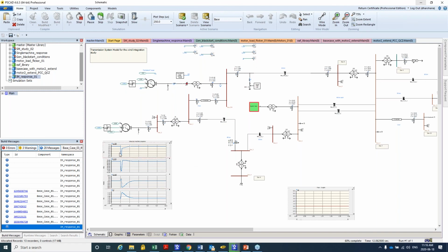And this delayed voltage recovery, the poor reactive power response, is because the rotor winding is just shorted. In a synchronous machine, the field winding or the rotor is connected to an electric supply, the DC field. So through the field winding, you can control your voltage response or the reactive power response. Induction machine, you can't do that, right? Your rotor winding is just shorted. So that's why type 1 machines went out of favor, but the type 3 DFIG became popular, because in DFIG,